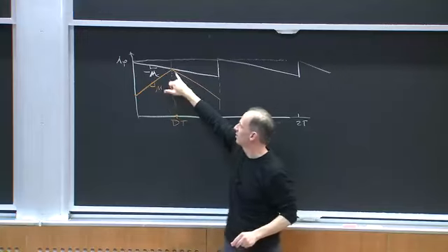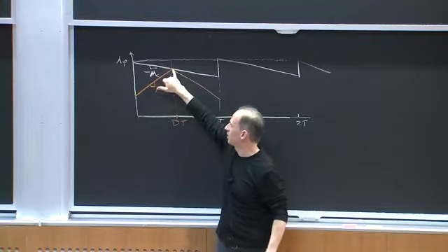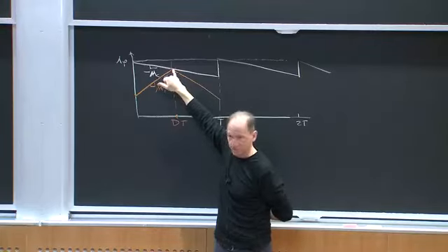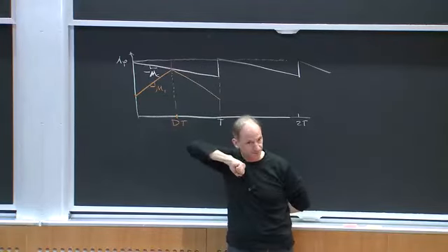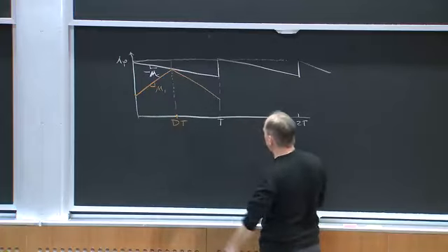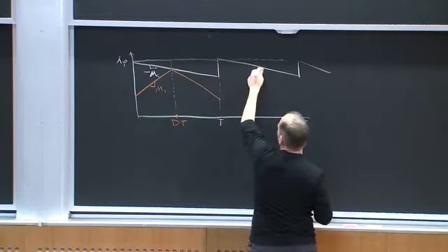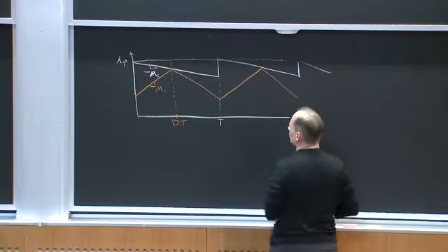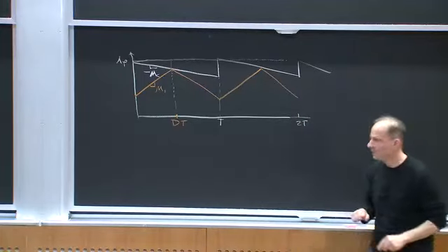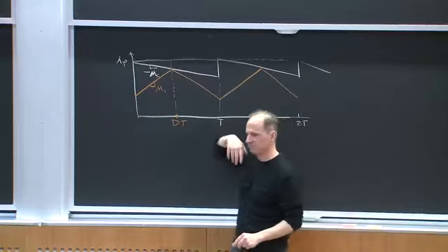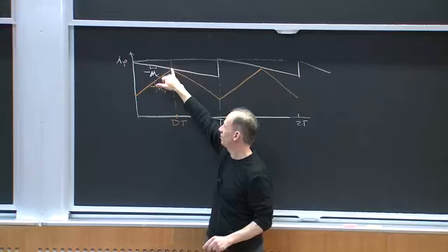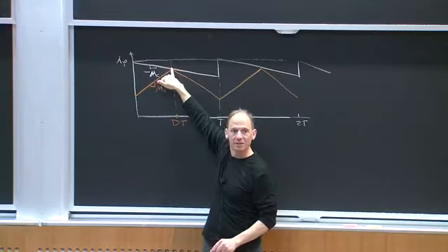Say this is dT. The switch turns on at the beginning of the cycle, but instead of me setting a duty ratio explicitly, I'm going to implicitly determine the duty ratio based on this peak current. Then at the beginning of the next cycle, I do the same thing: I turn the switch on, it rises, it falls, and I get the same general behavior. It's just that instead of turning the switch off after some time dT, I turn it off implicitly when it hits some current that I command. Any questions about that?